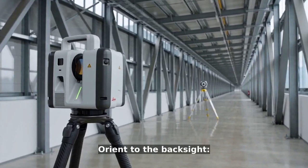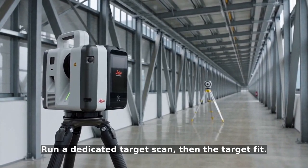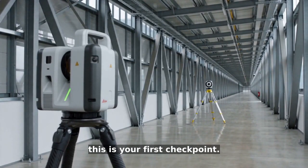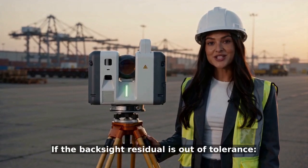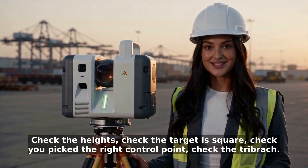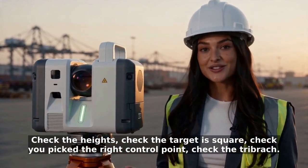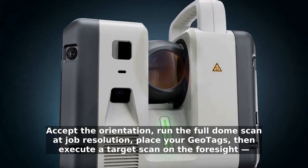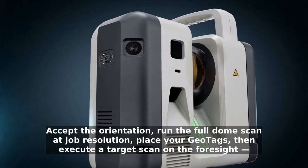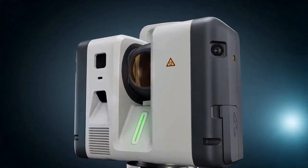Orient to the backsite, a force centered target on the known point. Run a dedicated target scan, then the target fit. Then review the residual. This is your first checkpoint. If the backsite residual is out of tolerance, stop, do not scan. Check the heights, check the target is square, check you picked the right control point. Check the tribrach. Accept the orientation, run the full dome scan at job resolution, place your geotags, then execute a target scan on the foresight and name it unambiguously.